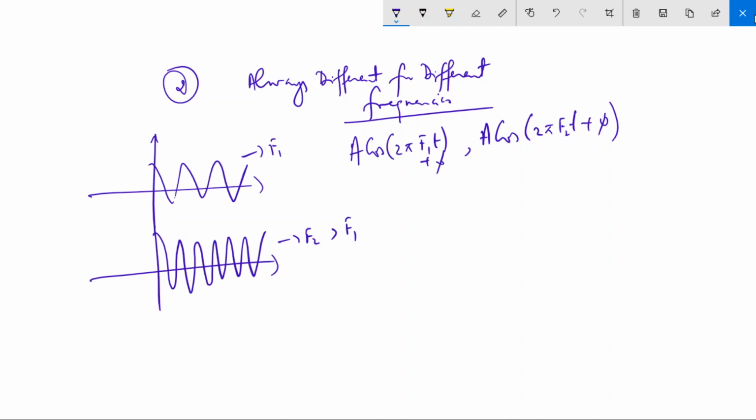So for any two frequencies, the signals themselves are different, whereas this is not the case in discrete time. Okay, why am I explaining these things? Because when you see discrete time, the situation is totally different. Continuous time sinusoids and complex exponentials are always periodic, but in discrete time they are not always periodic. That is the first difference that you will see.